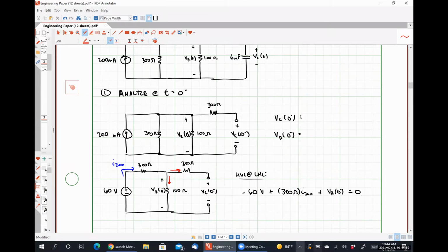All right, what's the current flowing to the right through the rightmost 300 ohm resistor? You mean like the one that's going through the 300 ohm? The one in red that's going through the 300 ohm, yes. Yeah, it wouldn't be anything because it's not ground. It's not in a completed loop. Exactly right.